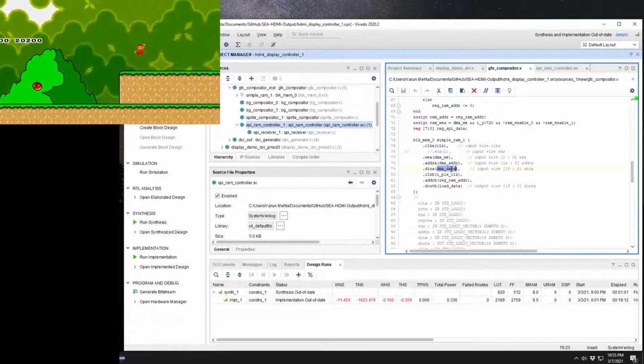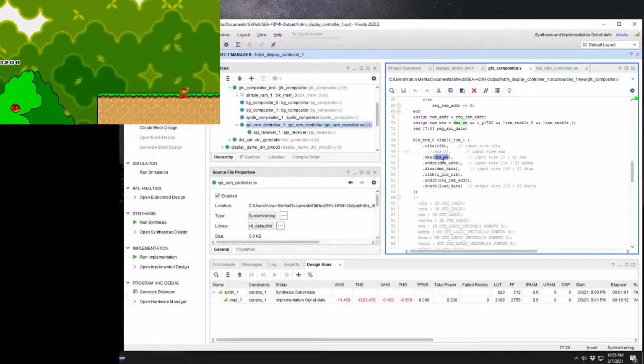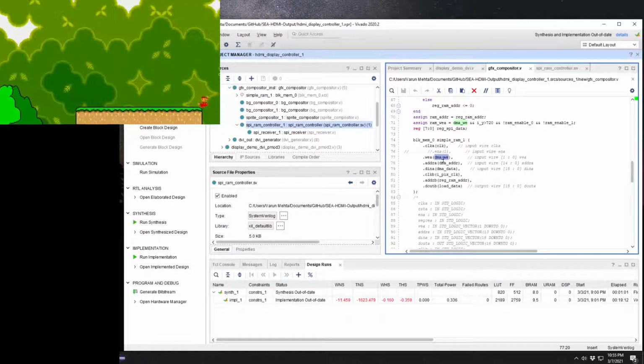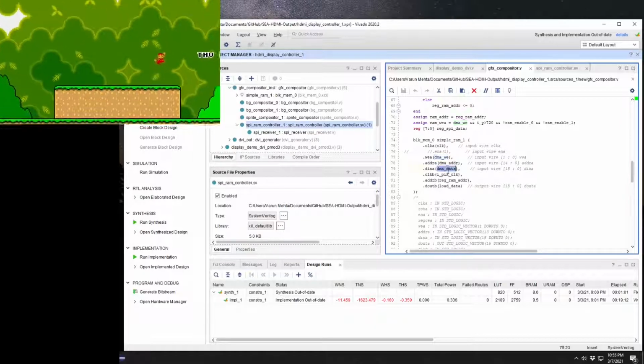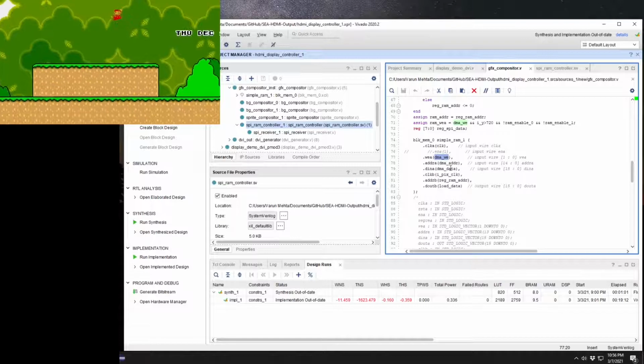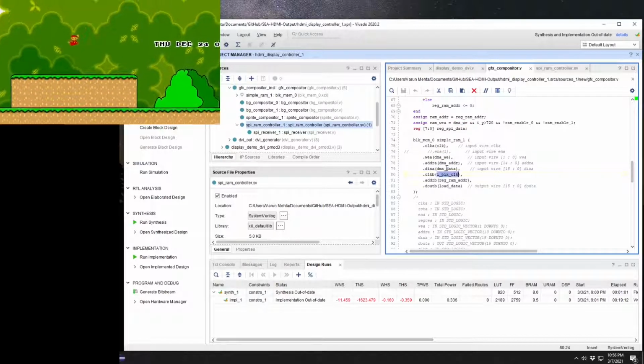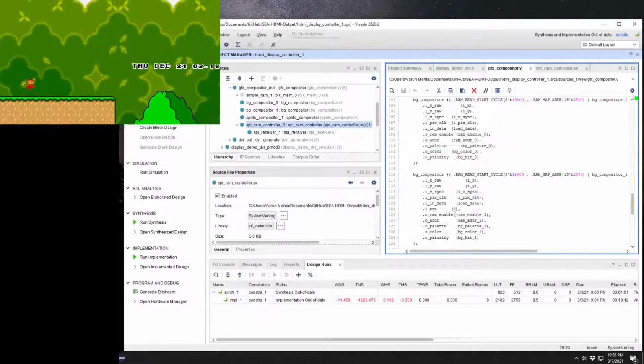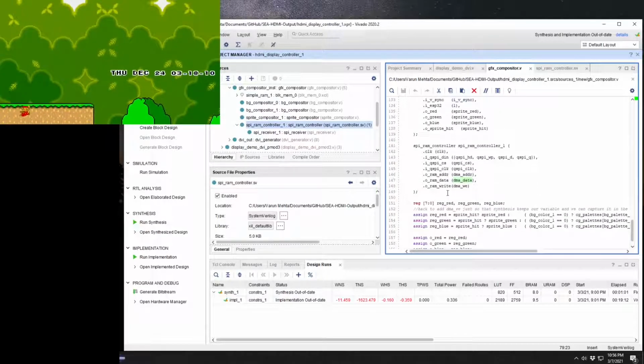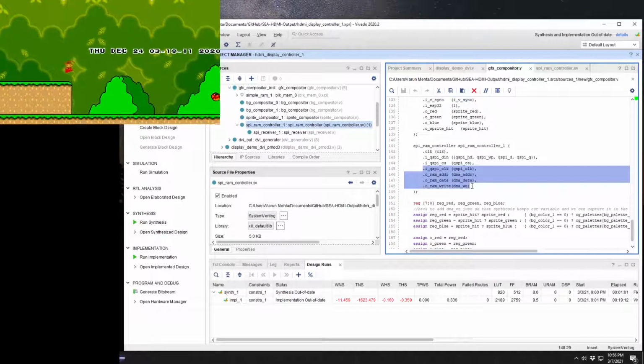Basically, it kind of works similar to DMA in that there's no processor that's writing this data, so it's dedicated hardware. So I went ahead and called it DMA style writing. So there's a write enable, address and data, and each of those comes from our SPI-RAM controller down here.